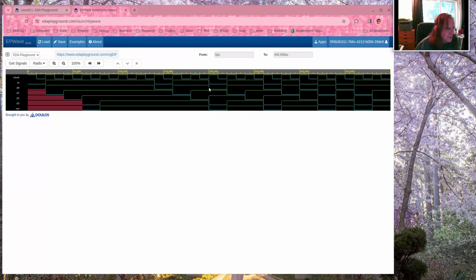The input value is being slowly shifted through and appears in the output. So here's our original input, there's our output. Here's where the input was high, there's where it appears on the output. And then we have a low pulse followed by a short high section. Well, there's the low pulse, short high section, and then another low pulse right here, which comes out here, and so on. So that's a working shift register.